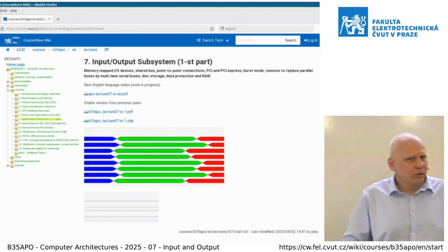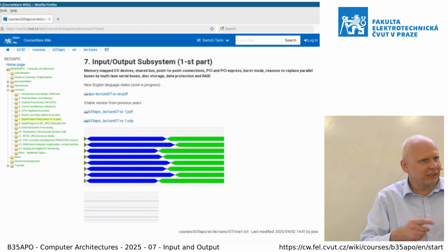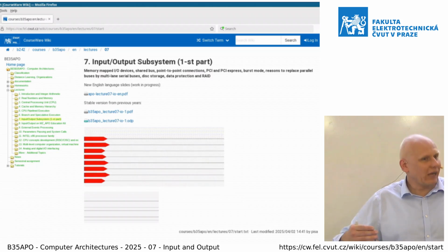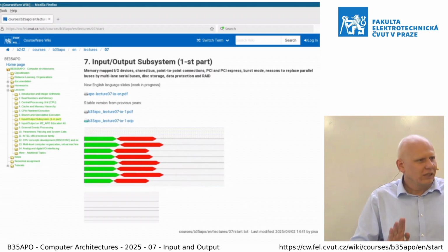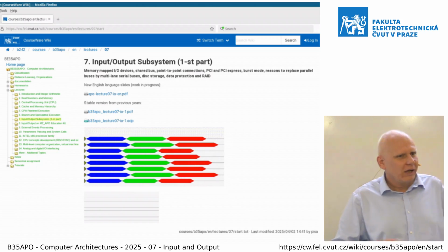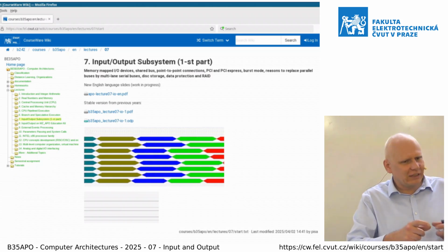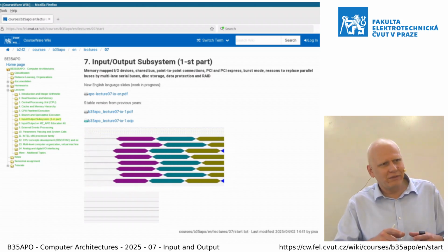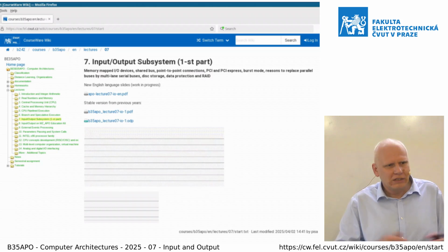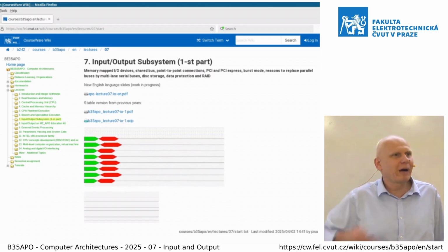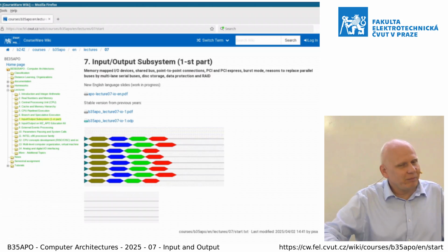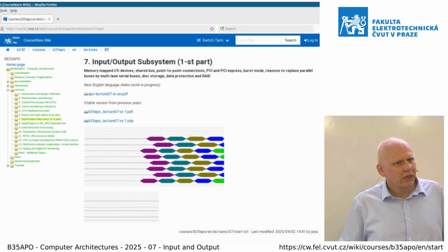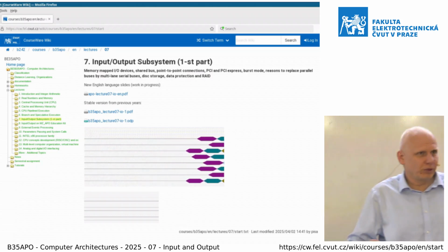So you have buffers which receive the individual bytes from the individual lanes and then need to put them back in the correct order. You still need to know which byte is which, and if there is a shift bigger than defined, I think 1 byte time or a little more, then you are in trouble. But it is 10 times later than in the parallel case. So you can go faster.